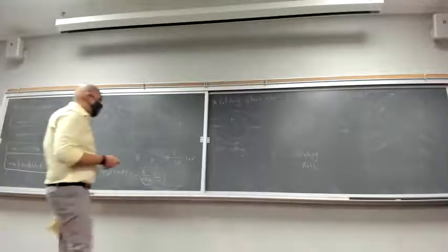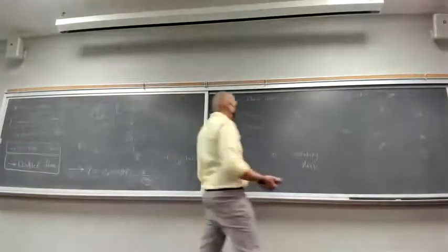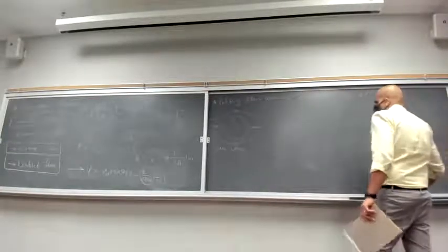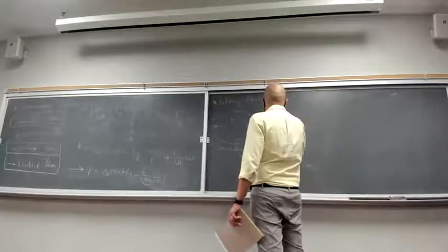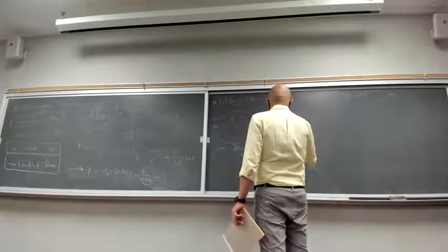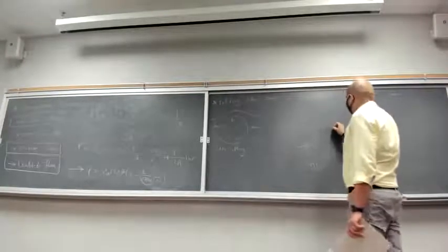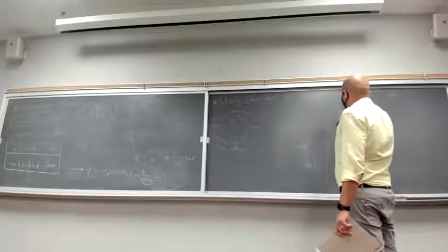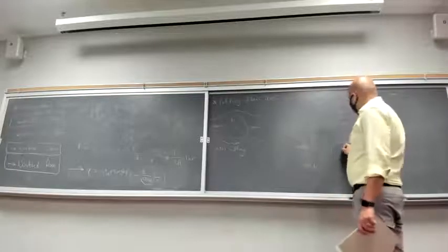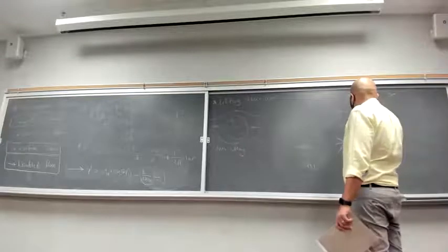Muhammad is asking whether, instead of replacing this non-lifting flow with a uniform flow and the doublet flow, whatever that looks like, we can replace it with the uniform flow and the source flow. That's what you're telling me, right? Is this correct? Yeah. Or sink flow, whatever.